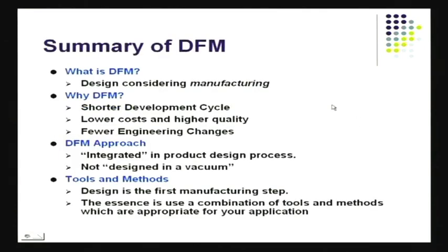So what is the summary of DFM? If we summarize this very quickly, it is design considering manufacturing, because my eventual goal is to be able to manufacture that product. What are some of the advantages? We will end up with shorter development time, lower cost, higher quality. These are some of the things coming out of this. And there will be fewer engineering changes, which will not be there if you do not go the DFM route.